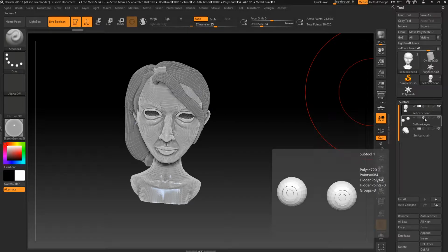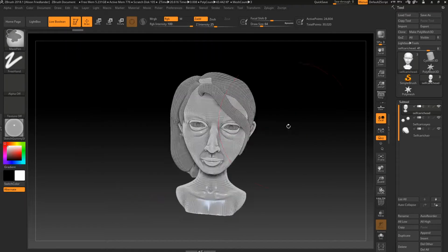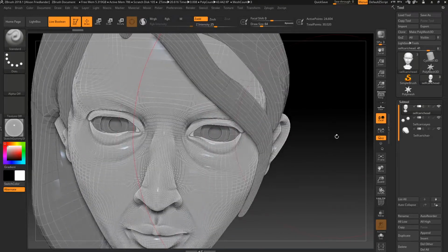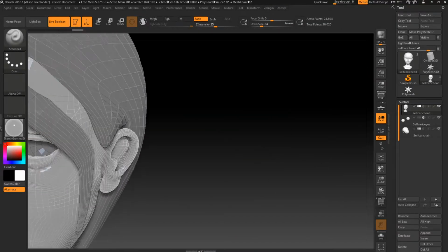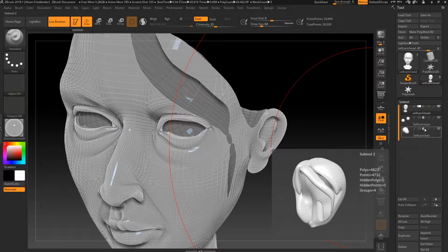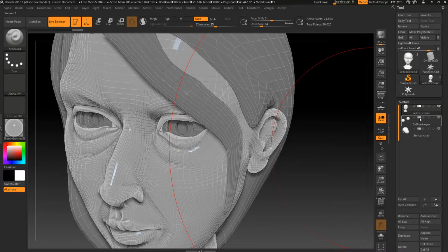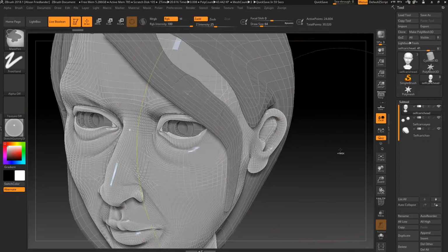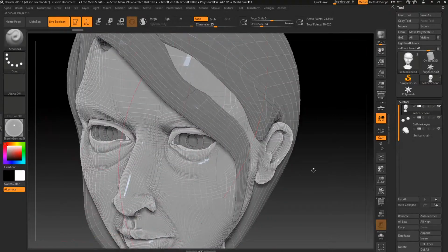So again, in this case, Live Boolean is really, really cool, because you can actually see without actually calculating any Booleans. Like if I take the eyes and set that to be different, the middle icon, you can preview that it's chopped out part of the head in the shape of the eyeball. So it's surprisingly responsive. And it doesn't commit any of these changes until you actually select Boolean, do the thing. So this is basically just a preview during Live Boolean.